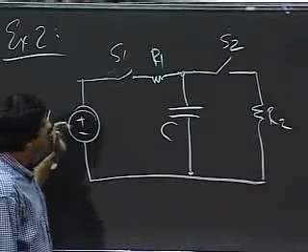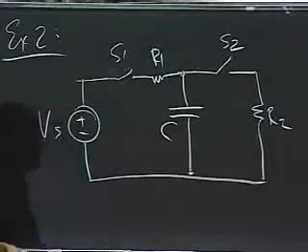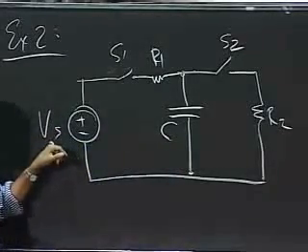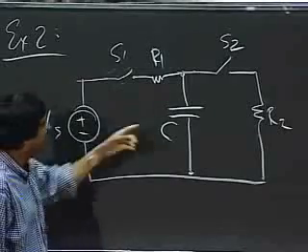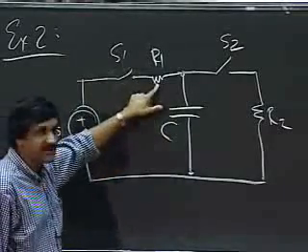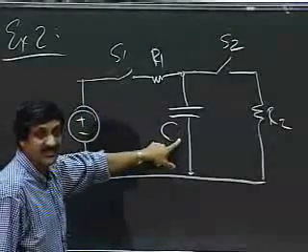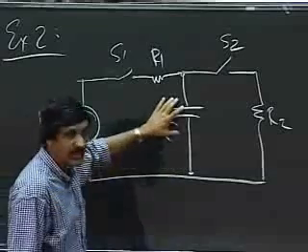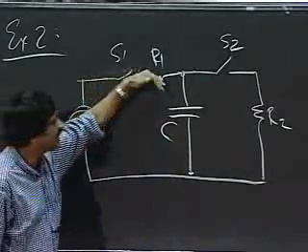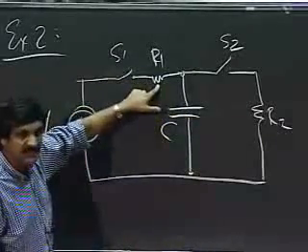Okay, and then, let's say I allow T1 to be as large as possible. And so this capacitor is going to be charged up to all of Vs. So after a long time, this guy gets to be Vs on the capacitor. And as it's charging up, I have current flow through the resistor, so it's sitting there dissipating power. Notice that this capacitor does not dissipate energy, it simply stores energy. So the energy supplied by the voltage source comes in, some of it gets stored in the capacitor, and some of it is being dissipated by the resistor.